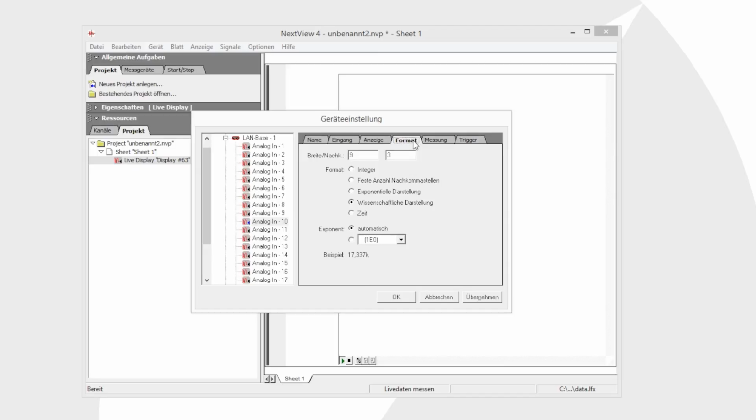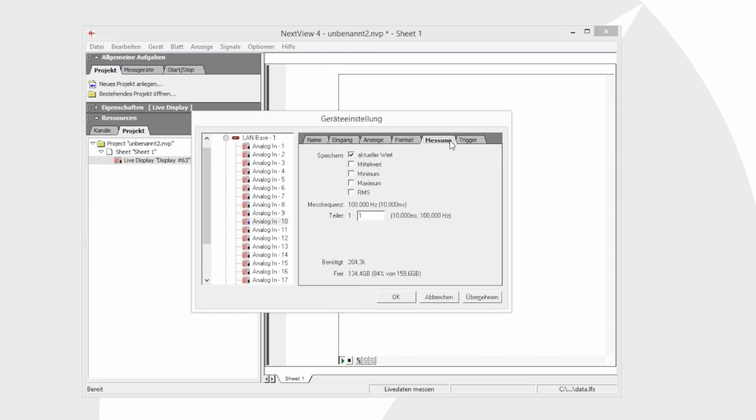In the panel Using, you will find all settings regarding the formatting and display of the measurement value. You can set the minimum shown length or number of decimal places manually. If choosing the exponent by hand, you can display a fixed unit. If you would like to see just kilograms and tons in the example, you would have to adjust the settings accordingly. There are several options on how to save your measurements.